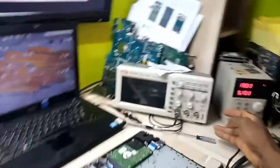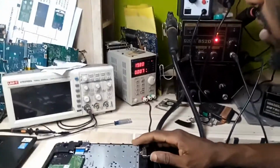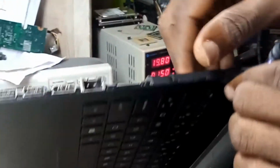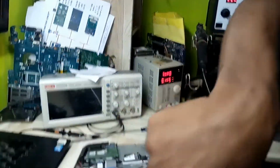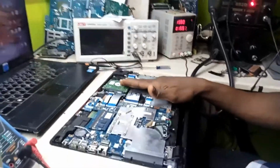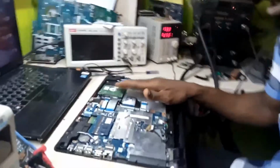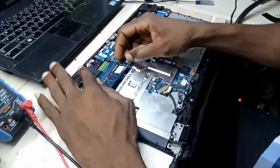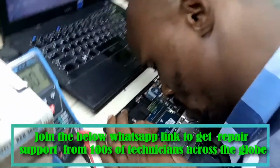So now again I'll power the board and give power. Now this is the consumption. Let me check if it is caps locking. Okay, still caps locking. The consumption has only changed because I've disconnected the hard drive. So what I will do next is check the requirement of this section, and to do that I will have to go through this board schematic.